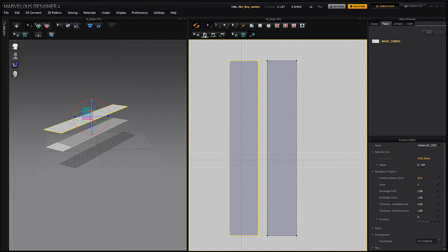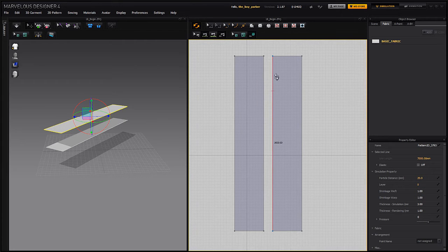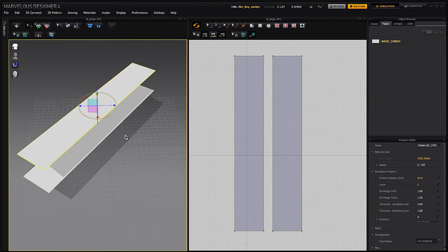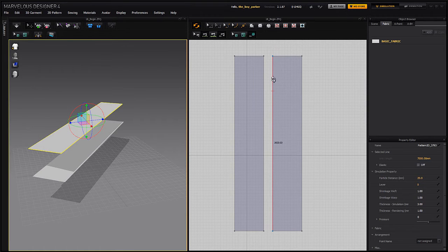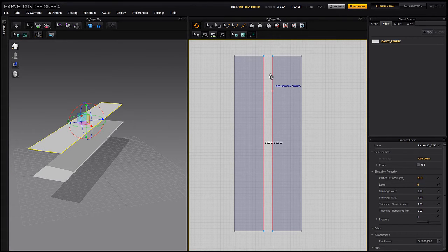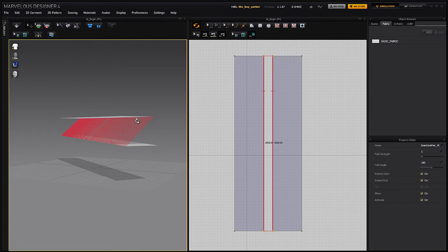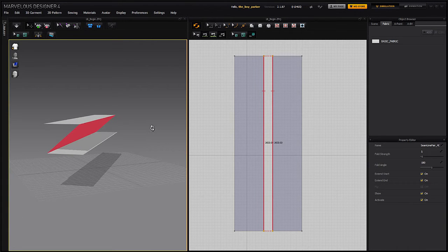So this little sewing machine is the segment stitching. You'll get the hang of this quite quickly, I think, once you've given it a few tries. Let's just say we pick this edge and we want to stitch it to this edge, and we'll see it's stitching the wrong edge to the wrong edge because they're sat right next to each other, because we picked this one up and copied it. So that edge would stitch to the outside edge, and that edge would stitch to this inside edge.